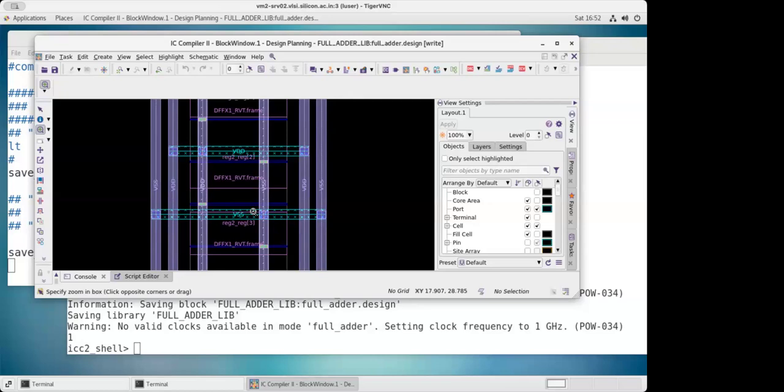Okay, then power planning dot tcl is not present. You're saying we could not open. Can you just do the ls? Okay, do the ls space scripts and tab. Again, press the tab button. Tab button, ma'am. Here, this is the tab. Okay, enter. So you have power underscore planning, ma'am. Power underscore planning dot tcl. Is it clear?